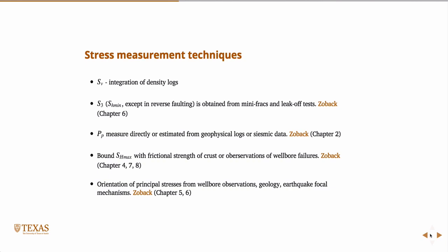Later we'll look at wellbores, and wellbores almost ubiquitously always have some breakouts, some region where the rock is beginning to fail. That doesn't mean that you have an unstable wellbore. Many times, that can lead to wellbore instability. If you have lots of breakouts such that essentially the wellbore collapses on itself, that would be a bad thing.